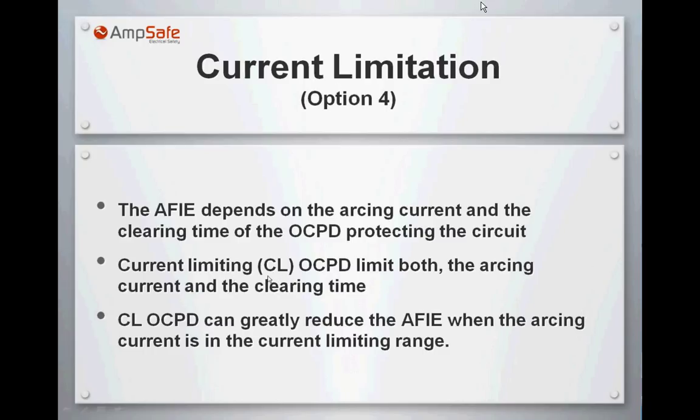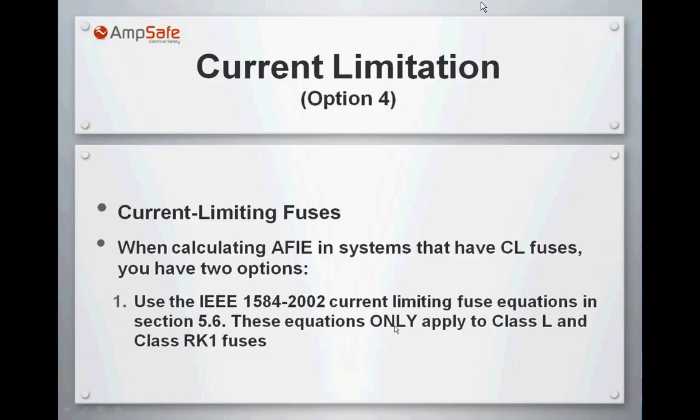Okay, so let's go to the second slide after this. Now that we know that it's very important to consider the current limiting effect of fuses, we need to know how to do it. Well, we have pretty much two options to consider the current limiting effects of these fuses. Okay, the first option is to use the IEEE 1584 equations. These equations are in section 5.6 for current limiting fuses. This is very important to understand.